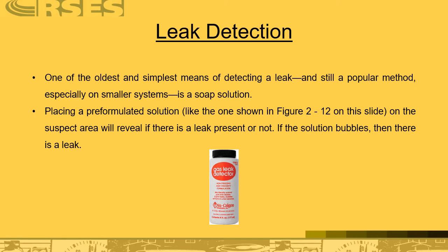Now, one thing you've got to be careful about: there are some soap bubble solutions that contain petroleum solvents. They should never be used with oxygen, because the petroleum mixed with oxygen can cause an explosion. Please read the manufacturer's MSDS sheets before purchasing this type of soap solution. This doesn't happen very often. Most of the soap bubble chemicals are compatible with different gases, including refrigerants, when doing leak detection.